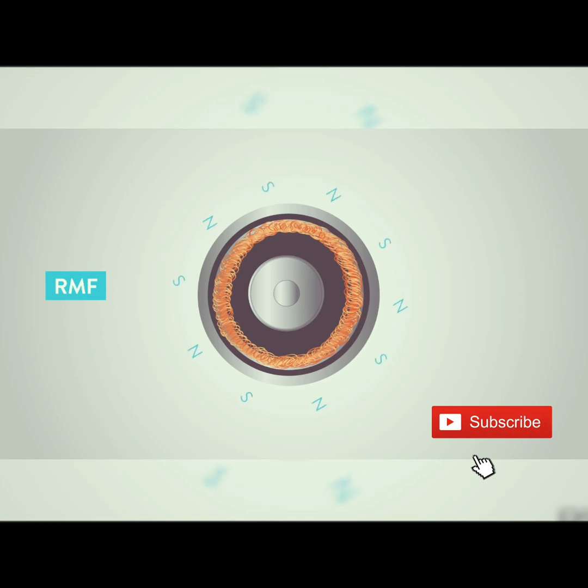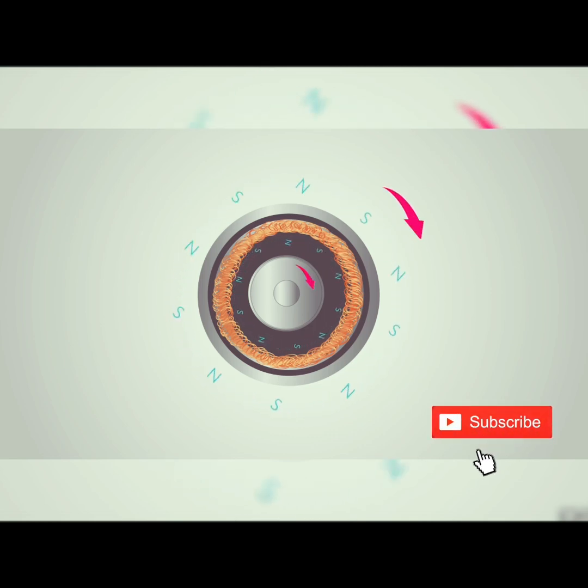The relative speed between the stator rotating magnetic field and rotor conductors causes an induced electromagnetic force in the rotor conductors according to Faraday's law of electromagnetic induction. This is the same action that occurs in transformers. Now, the induced current in the rotor will also produce an alternating flux field around itself. This rotor flux lags behind the stator flux. The rotor rotates in the same direction as that of the stator flux.